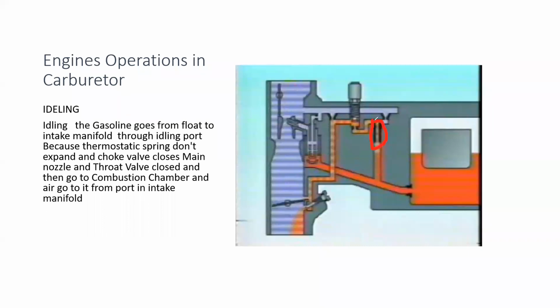This is the jet valve, and the jet valve sends the fuel through here, the metering jet, and it goes up this line, and from there fuel comes here, right? Fuel comes here, and it goes through here.